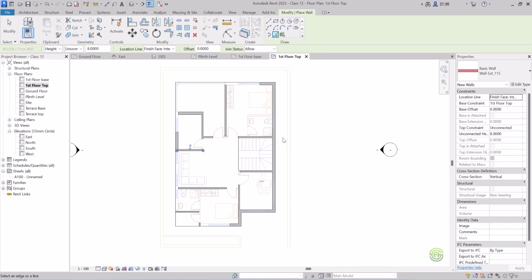If you just want to take interior shots, then you can create an interior room and take interior view shots. But in Revit, we are creating everything. So when you go to a section or elevation, you can preview everything. For that, we have to create all the walls at the same time. If you want to see a section of this file, it will be easy if you create interior walls as well.